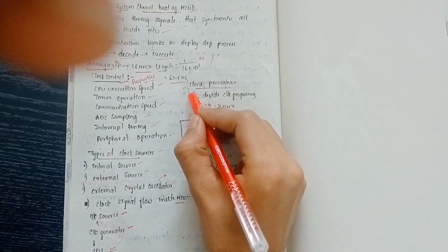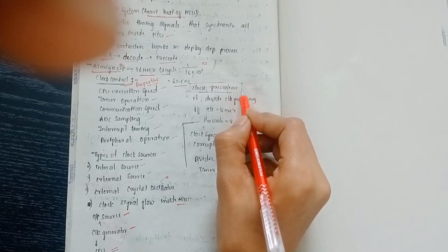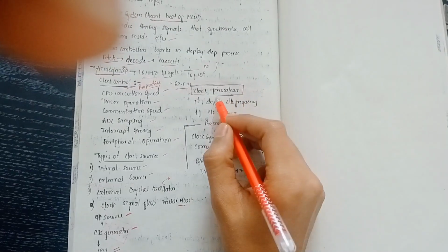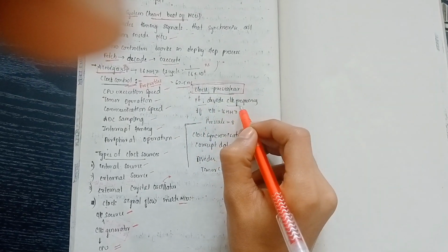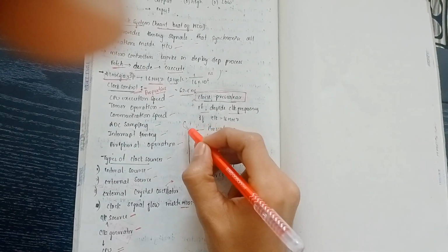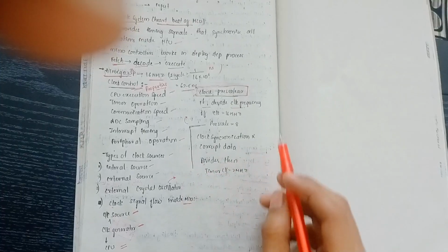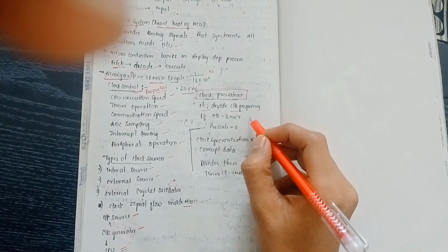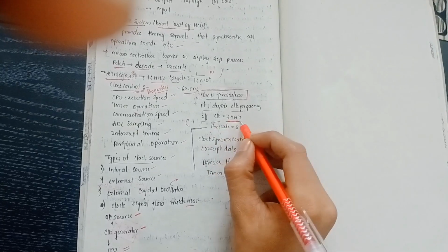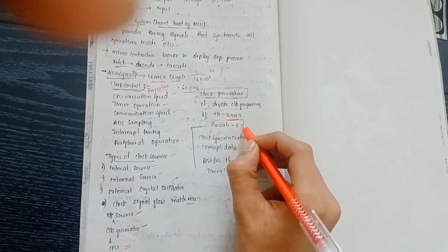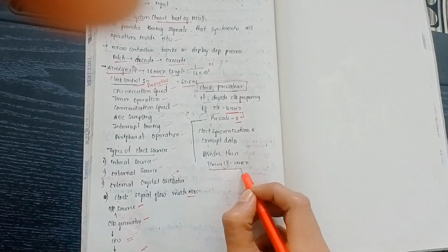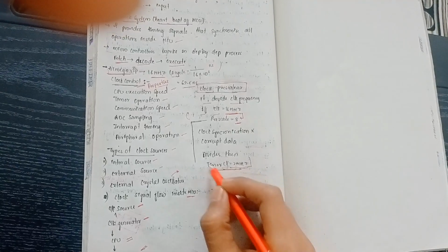The new type of technology which is being implemented recently is the clock prescaler. It divides the clock frequency so that it does not waste excess power to perform a task which can be done at lower frequencies. Assume a clock which works at 16 megahertz. It would be prescaled to 8 megahertz, and now the timer clock can perform the same task at 2 megahertz.